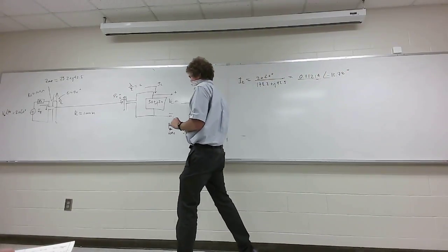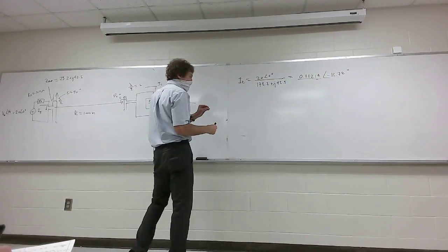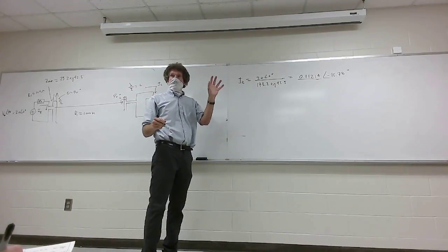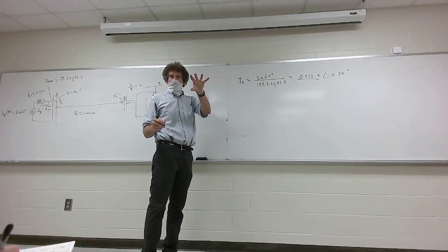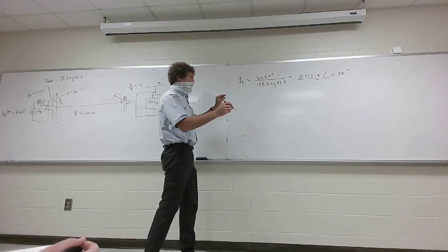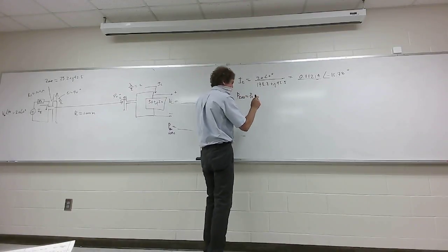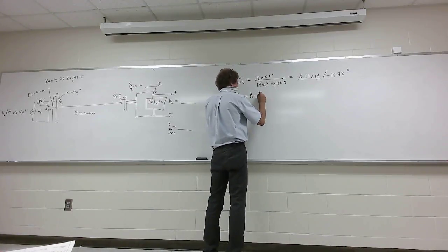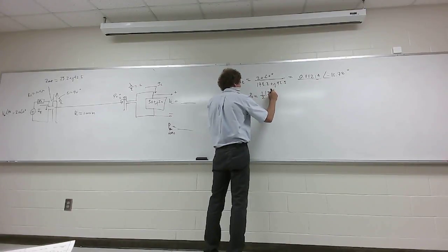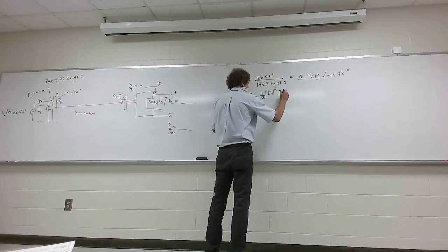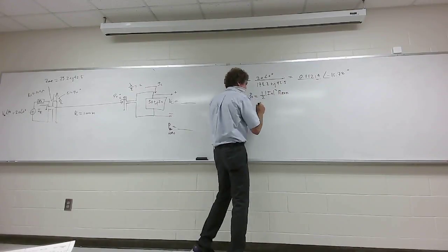And that angle will not matter. Now, the next thing I wanna do, y'all agree that's the current, right? Now I wanna find the total power transmitted, or radiated. So P radiated from the source, or P transmitted, either one, is equal to 1/2 the magnitude of I of the transmitter squared times the radiation resistance, right? Y'all agree with that?